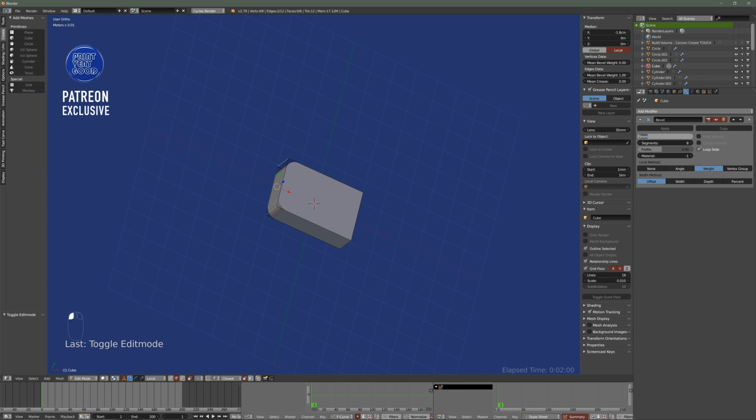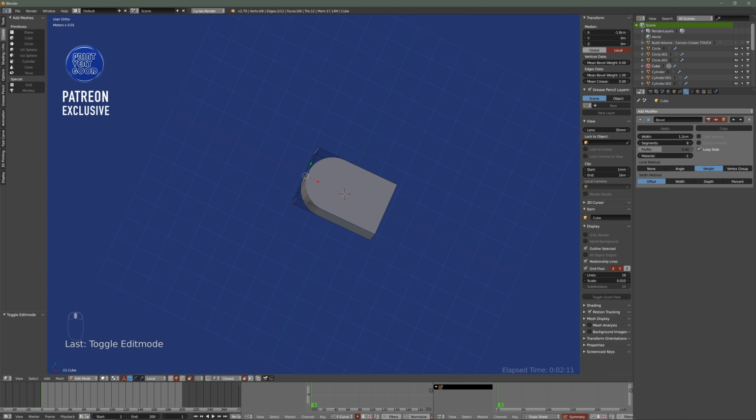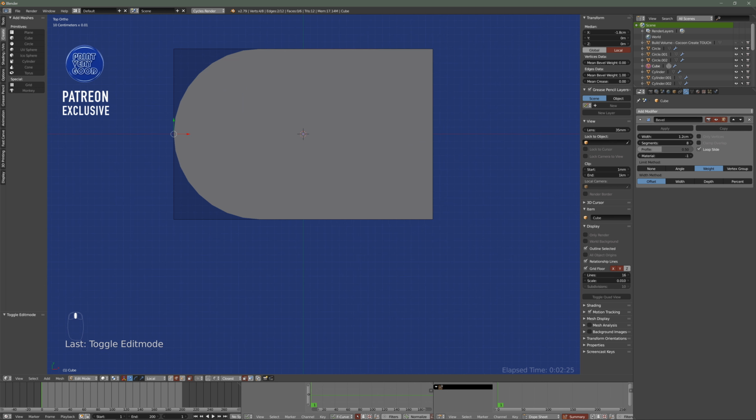And I know this is a 12 millimeter radius curve that we're looking for here. So I'll make this setting here 12 millimeters. And that should give me a 12 millimeter radius arc on this section of the heart. So it'll be 12 millimeters down and then 24 millimeters on the straight edge. And if I zoom in, I can see that I count off my squares on the bottom left hand corner on the background grid, it'll count out to 12.